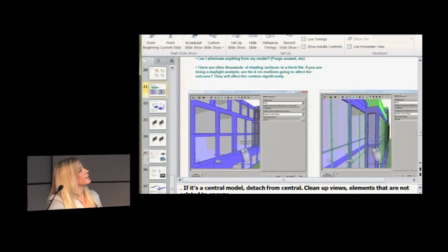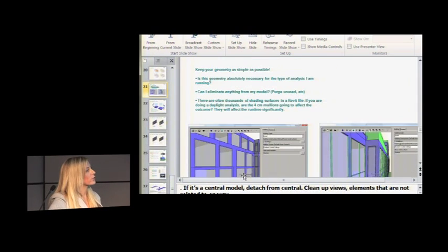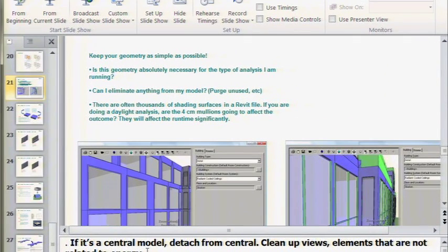It has nothing except for what bounds a room. So if you add any shading, it's not coming through. Parapets are not coming through. I'm hoping that's the same word here. And all sorts of details are just going to be ignored. Mullions, even where it divides the window, that's going to be ignored. But for an early stage analysis model, this might be what you want. You can just run it very quickly. You can pull it out.